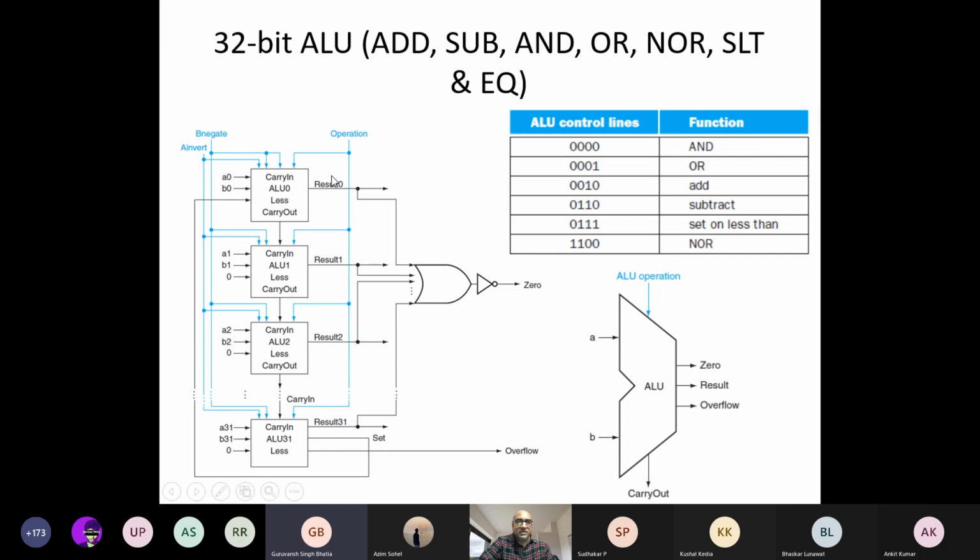You will get the output of the subtractor will be 0. But here we have to indicate that in a different form: you take the output of all these bits and give it to the OR gate, or the NOR gate, because the outputs will be all zeros. Then when you OR all these zeros, again it will be 0.